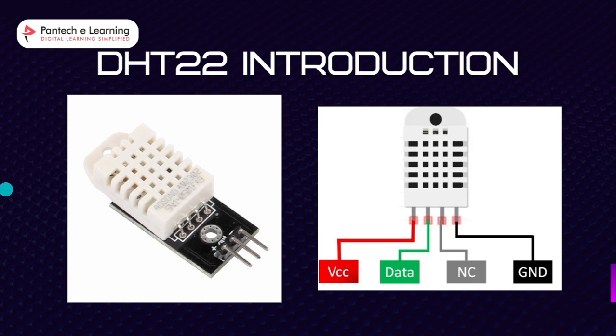And coming to its pinout, this image shows the pinout diagram of the DHT sensor. So the DHT sensor consists of 4 pins. But on the DHT module, only 3 pins are exposed to the pinout of the module. And the 10K ohm pull-up resistor is internally connected to pin 2. Okay. So the following is the list of the pinout of the DHT sensor and a brief description. Pin numbers start from left to right when you hold the sensor from the front end. So it shows how these pins will be connected with the STM32 Nucleo board.